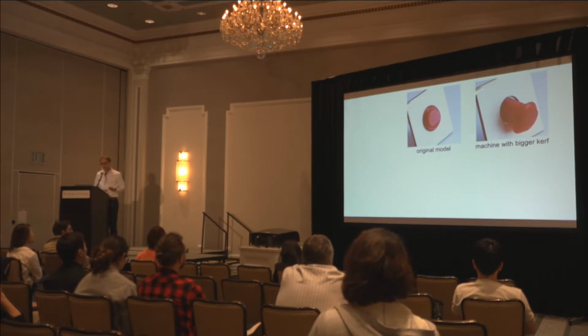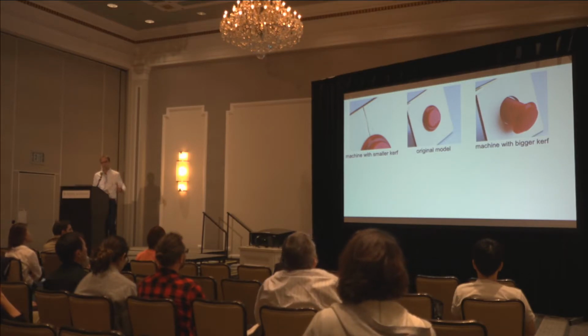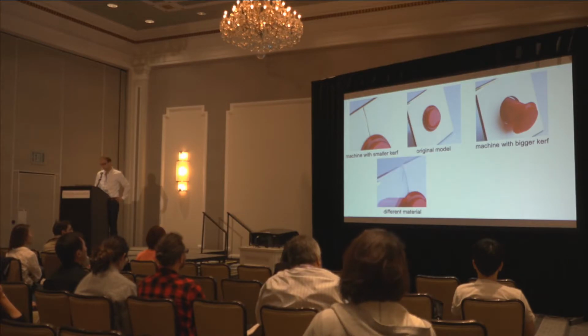However, if you use a different laser cutter with bigger kerf, there's a chance that the button will fall out or will not mount tightly in place. And at the same time, if you use a machine with smaller kerf, it could crack the material, it could break the surrounding material. And the same thing happens if you change the material or if your laser cutter is in a different state of wear.